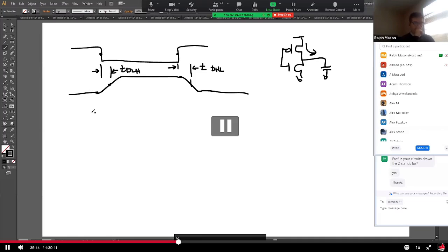So I need to use some equations here. I'm assuming that the transfer function here is a straight line. So we know from our basic circuits that I, the current charging a capacitor, equals C dV/dt, or delta V over delta T, right? Remember that equation you learned for current and capacitance and voltage on a capacitance, right?